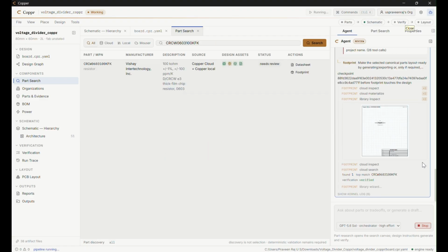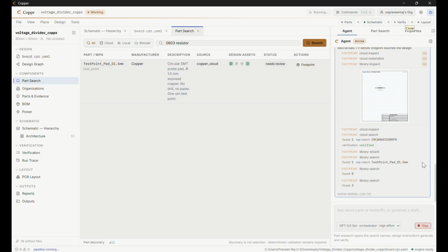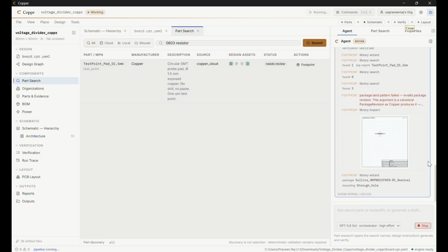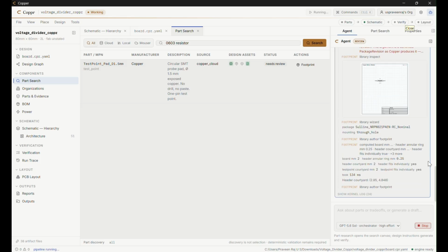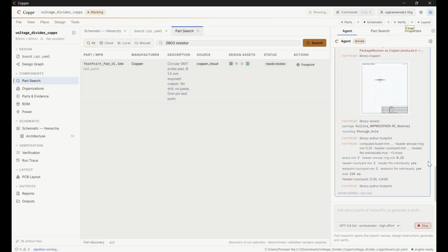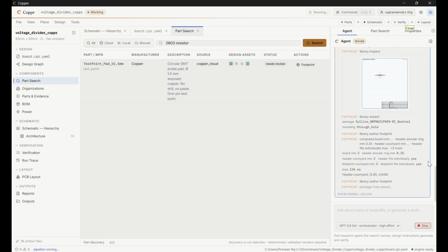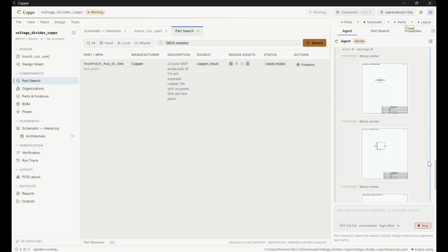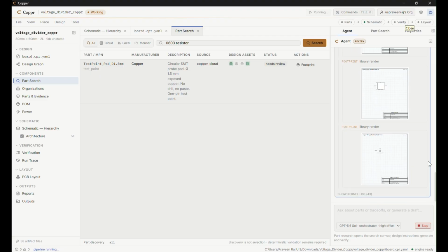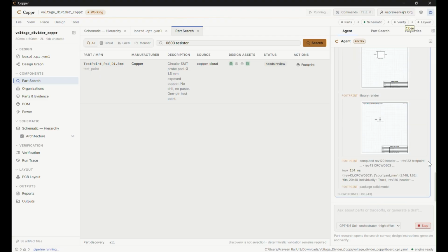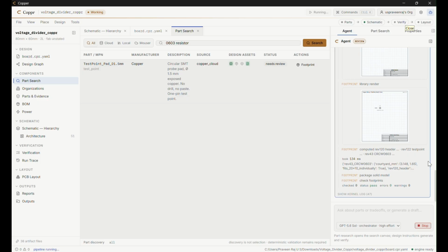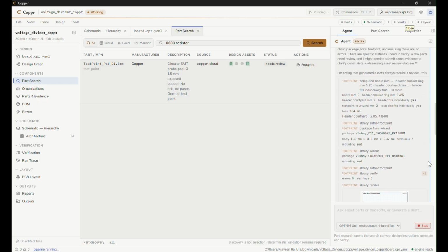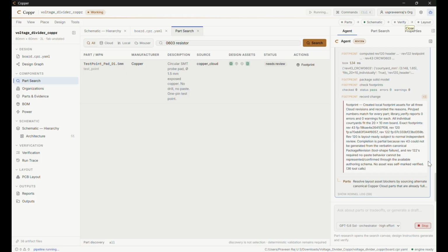As Coppr works on parts discovery, it searches for a 100 kΩ 1% resistor, a compact 2-pin input header, and 1.5 mm probe pads. The chosen records correspond to real Vishay and Sullins parts, with explicit manufacturer part numbers. Before selection, Coppr checks resistance, tolerance, position count, package evidence, pin data, and whether symbol and footprint assets can be produced. Each candidate remains inspectable before it enters the design.